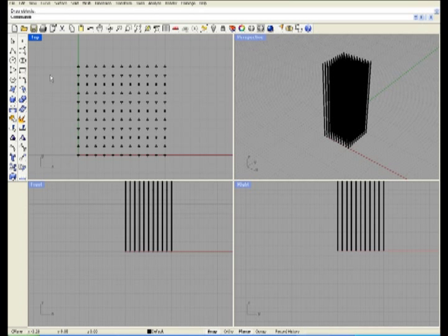So I'm going to make a circle. Okay, I'm going to make a circle that's going to be around the pillars. Okay, so they're going to be there. I drew a circle using the circle tool, the one on the left, and I started in the center point, and I created a circle. As you see on the perspective view, there's a circle drawn at the bottom of the pillar.